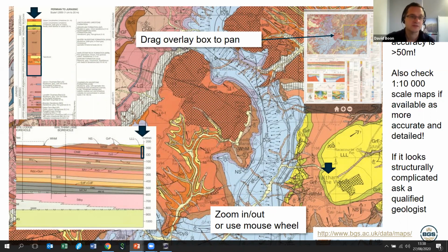You may encounter several aquifers, which you could potentially use for open loop schemes. You can use the mudstones, which are tighter and have less water in them, for closed loop schemes. So it just gives you a better appreciation of the 3D component of the ground.